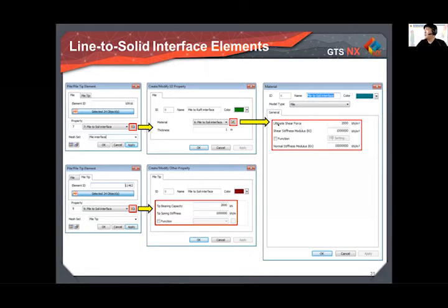As I mentioned, the first one is the ultimate shear force, and next one is the shear stress modulus, and the normal stress modulus is related to the pile interface behavior between pile and soil ground. And this one is related to the tip bearing capacity. So first one is the pile tip capacity value, and next one is the tip spring between pile tip and the soil.